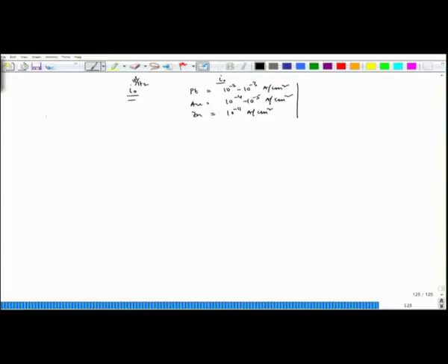Now, how are we considering this? For example, if we have two beakers, in one beaker we have a zinc plate, a zinc block, and the concentration of the electrolyte, that is acid medium HCl, is the same in both. In another case, I have zinc in connection with a platinum plate. This is the platinum plate and this is zinc. Now, we would see that in this case we would have a very high rate of corrosion of zinc. Why? This can be explained by using mixed potential theory.